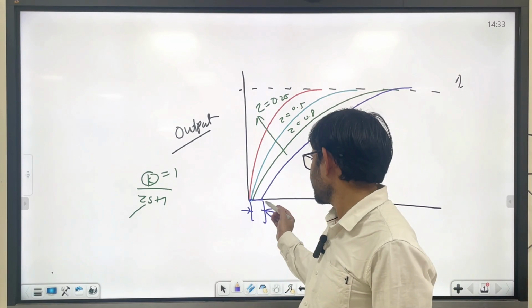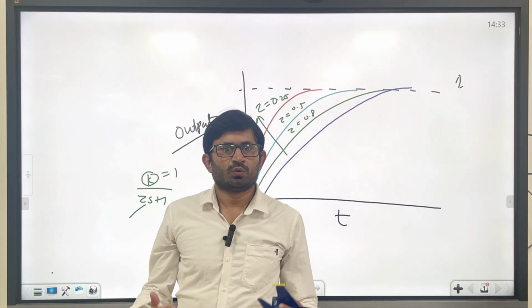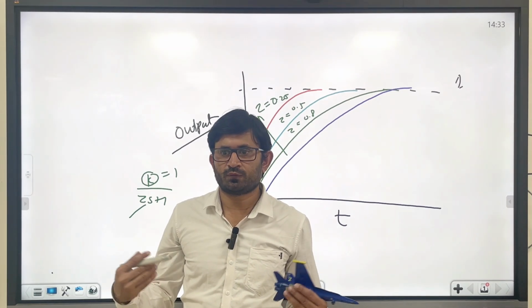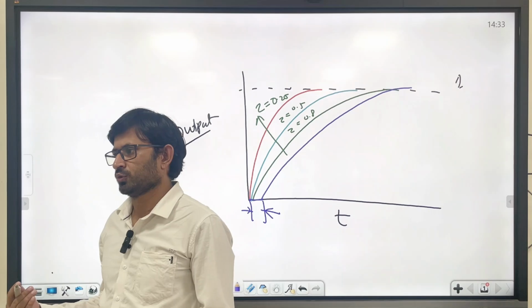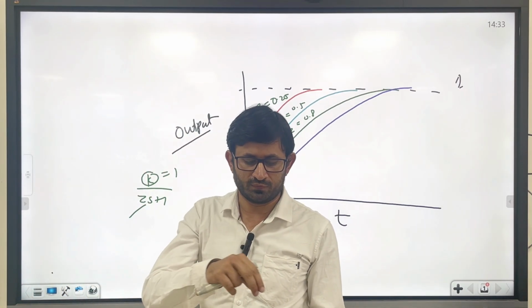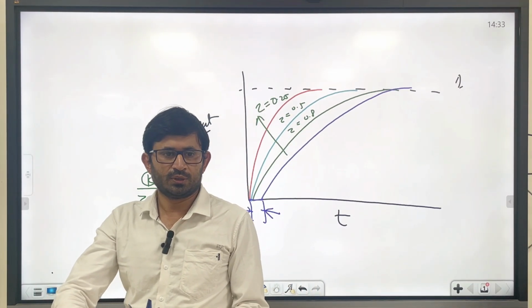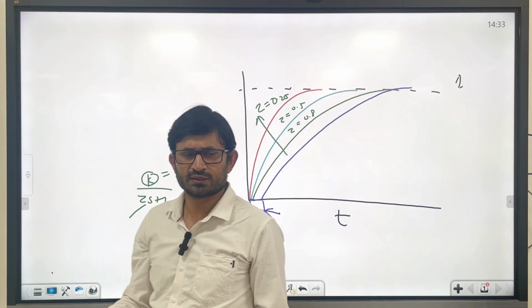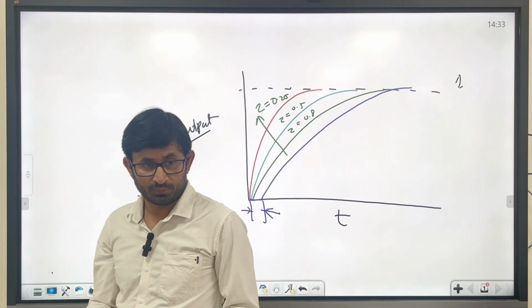Okay, you will see the delay in the time axis. So who is responsible for the delay? One is the sensor. The sensor takes time to send the data to the actual flight controller. Let's say you have designed the flight controller, which is the math block. So this is a velocity sensor, pitot tube. It will take some time to send the data. There is one kind of delay. Another is computational delay. It will take some time to compute.